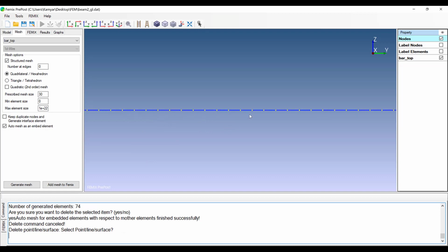Now, because the mesh is structured, it's not that much feasible here, but for stirrups and the Z bar, we will see what is the difference between meshing by automesh and meshing by Gmesh, which is defined by these parameters.